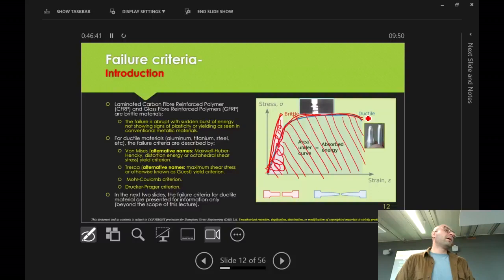One of the key issues that you need to bear in mind is the thermal effects. The thermal coefficient of aluminium, there's a figure for it, but for composites it's almost zero. I'll get back to you. So when it heats up, it elongates, not exactly zero, but it's very marginal, very small compared to aluminium. So when you've got these differential temperatures, it will create stresses and debonding.